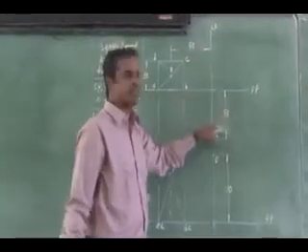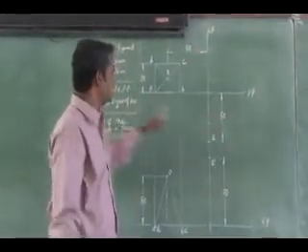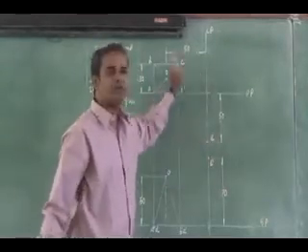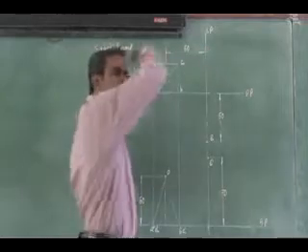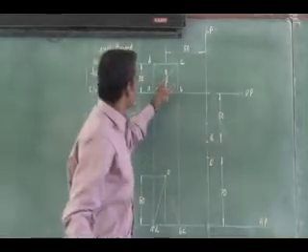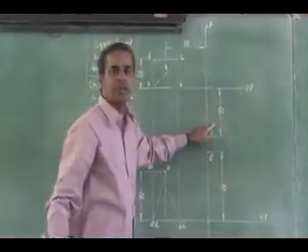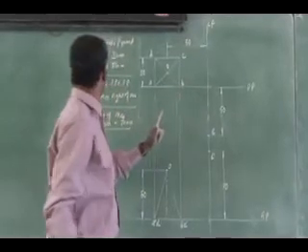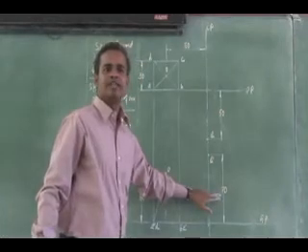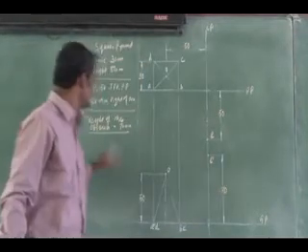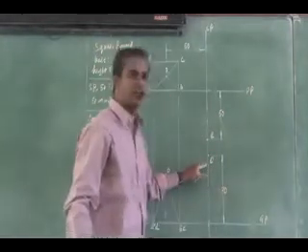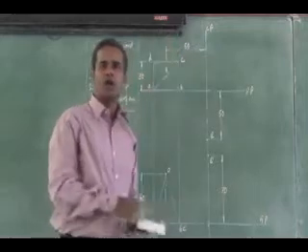Now this station point, as per the given condition, is 50 mm in front of the picture plane. I have marked E, and it is 50 mm to the right, so altogether the station point should come to the right of the axis. Then this 70 is nothing but the station point above distance, given here as the height of the observer, 70 mm. I have marked the dash. This is the layout I have drawn.